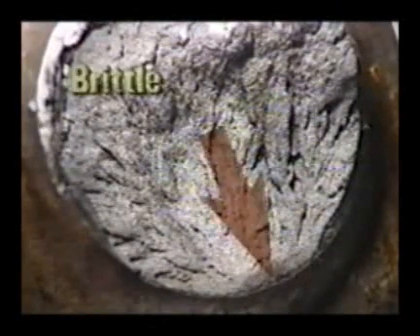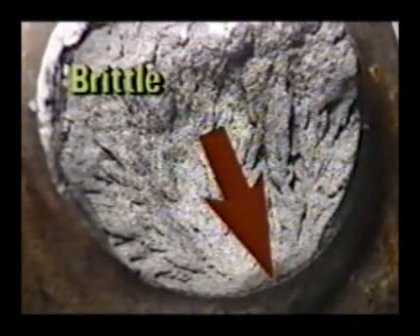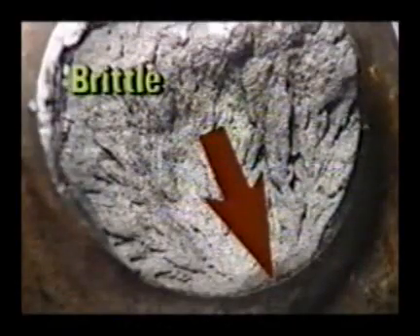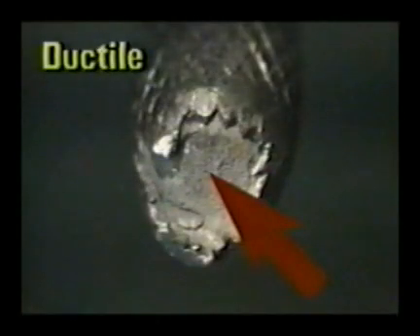If you said it is a brittle cleavage fracture with chevrons that point to the lower edge as the initiation site, you are absolutely correct. Can you identify this fracture and locate its initiation site? If you saw plastic deformation, shear lips, and a rough woody center, you probably called this a ductile fracture with an initiation site somewhere near the center.